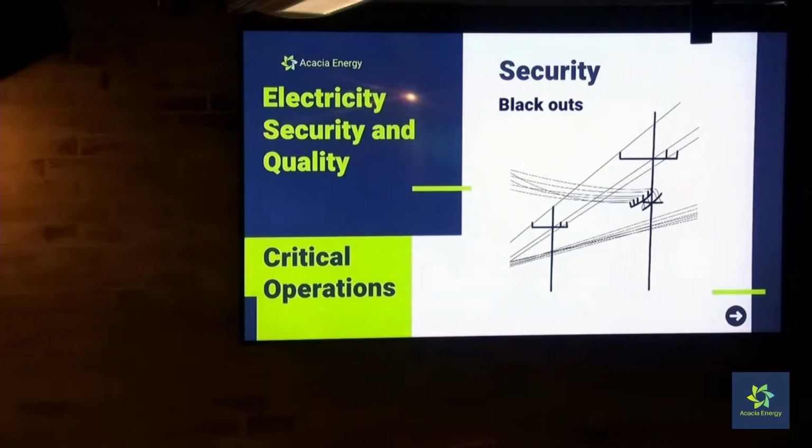And what we see a lot of on networks, especially on low voltage distribution or medium voltage distribution networks, is that all of the feeders connected to a substation, if you have another feeder that is impacted by a strike or a branch coming down, the network will operate what's called a recloser.